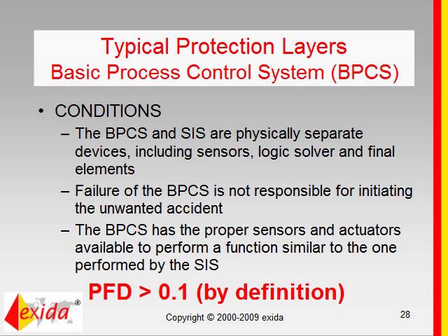You could also hire a third-party consulting firm. Exida is happy to do this for you and have those people do it. Or you could have maybe an engineering company that has some experience with the layer of protection analysis and have them do it as well. The key is, and this applies to everything that you do with regard to IEC 61511, that the person or persons that are performing a specific task as part of your functional safety lifecycle are competent in those tasks.